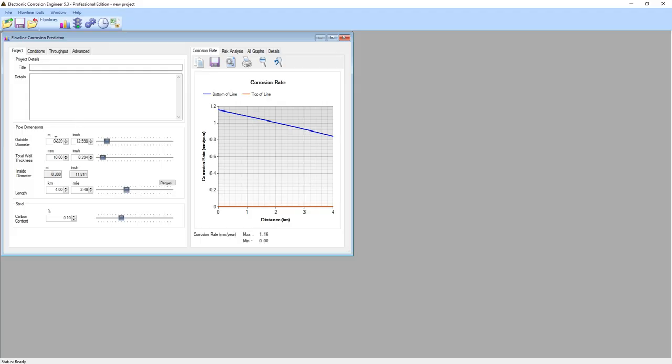Okay, by selecting the flow line project, a box like this will appear. Firstly, we should specify the outside diameter of our pipe, which is a vessel here. You may ask, are the flow line and the vessel exactly the same in corrosion analysis? The answer is clear, no. These two have different features in corrosion analysis, but as we have limitations in corrosion analysis software for equipment, we have to do just an estimation of corrosion probability in our system. And what I'm doing here is finding the overall reaction of the fluid with carbon steel in a somewhat similar environment to my pressure vessel.